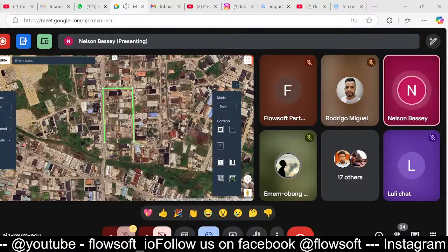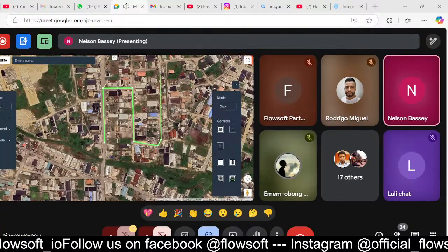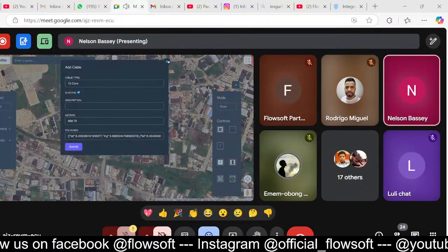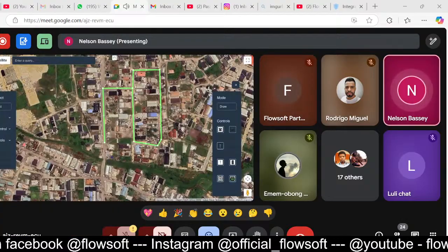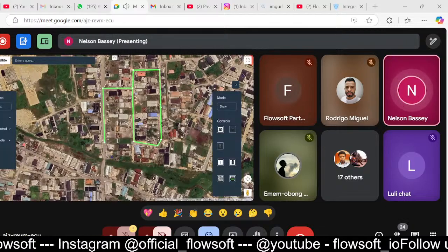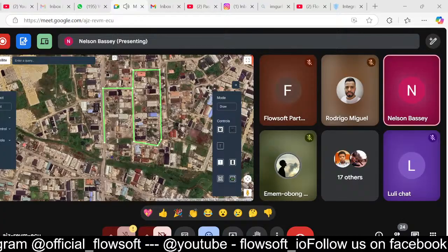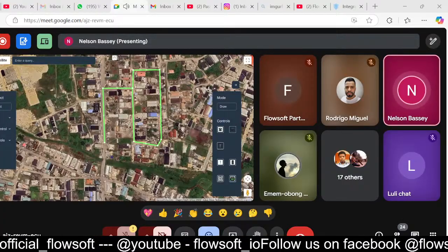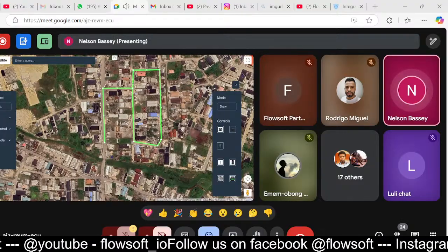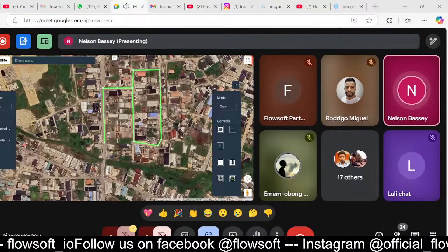So I'm just going to go here, here, here, here, and here, right? And then that automatically is how easily you can map out a network. And you can imagine that this is where your POP is, right? And you can use that as your output of the fiber, right? So this gives you in the back end the meters, right? So if it's a new project, you can know how many kilometers or meters of cables I need for this particular layout.